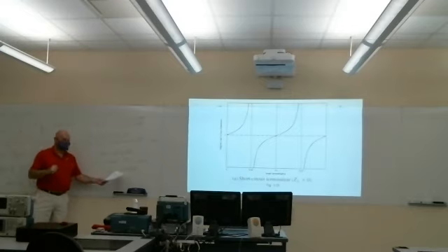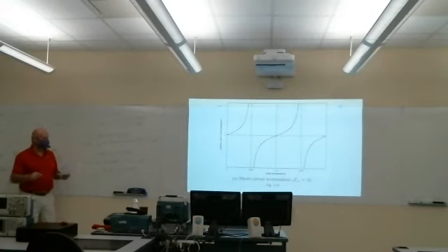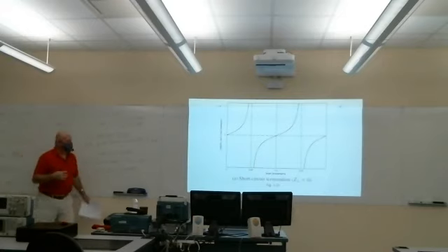The impedance of a capacitor is minus jX. But since tangent can go either positive or negative, when tangent is positive, Zn looks like an inductor. When it's negative, it looks like a capacitor at a certain distance from the load. And here we have just the opposite.